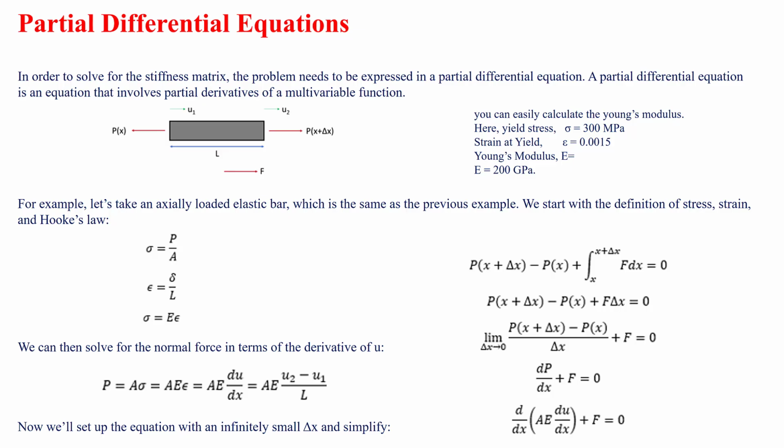So again, this equation can be reconstructed. We can see the load, which is equal to area into stress, and we can add up the stress value. It is AE by strain, where E is the Young's modulus.